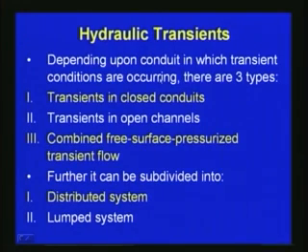Now, as I mentioned, in the case of a sudden valve closure, a wave is generated, the water hammer velocity is happening, and the wave goes back and again comes back. So, there will be a translatory movement between the closed valve and the reservoir, and then periodically wave action takes place.